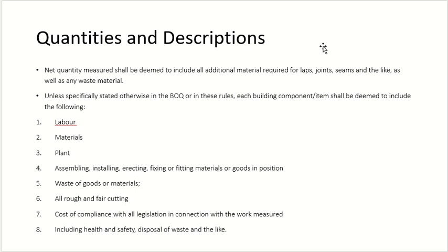That waste is taken as a percentage. You don't calculate the quantity: how many tiles will I waste here? No. I have 24 square meters of area, I need 24 square meters of tiles, and 10% of them will be waste. So 24 plus 10%, or 24 plus something percent. Got it? Okay. So waste material which you will waste, obviously this is part of the price you are giving. You cannot say I lost 2 tiles or 3 tiles, give me extra money for that. No, this is included.